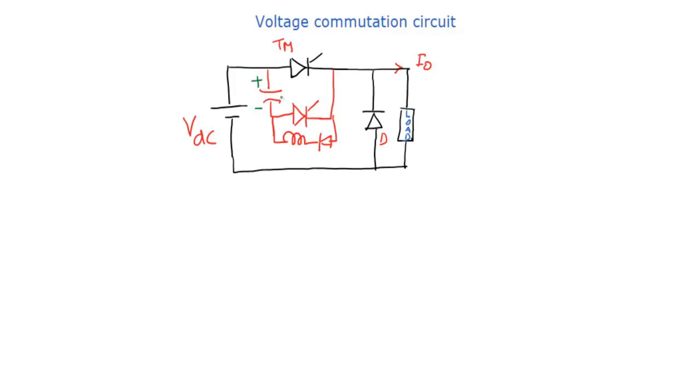So here, to turn off this thyristor, we require all this extra circuitry. That is called a commutation circuit. So one additional thyristor, then inductor and capacitor, nothing but the tank circuit. This circuit is required to turn off this conducting thyristor. That we can discuss. But before going to discuss other things, one of the assumptions is that the load is always drawing a current of I0. That means it's a constant value. When the source is not supplying the current, the freewheeling diode will supply it, and then the load will have the freewheeling period there.